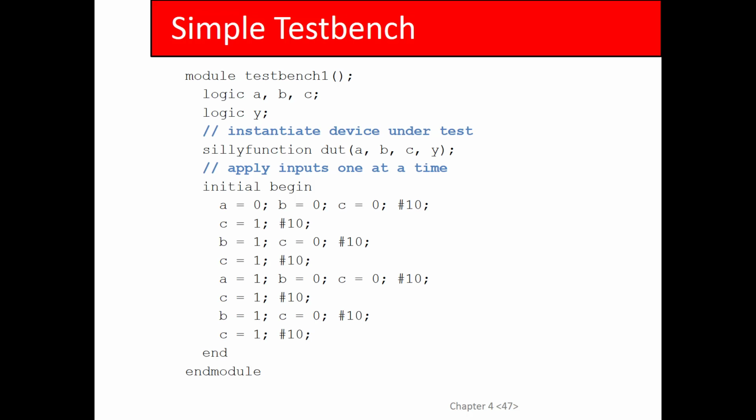There's not really a typical methodology for this. You always want to write a test bench to test your modules because otherwise, testing them is really difficult. You have to simulate them and manually force signals by hand. Sometimes you can write a script to do it, but it's best to write a test bench.